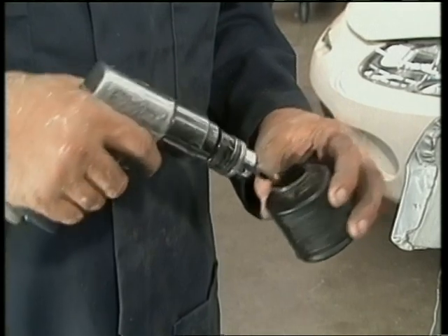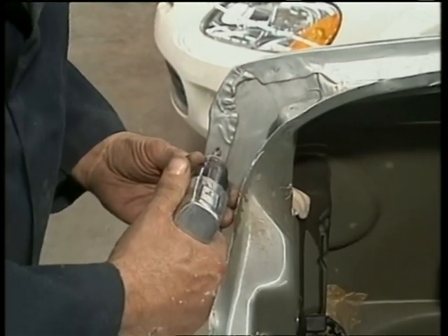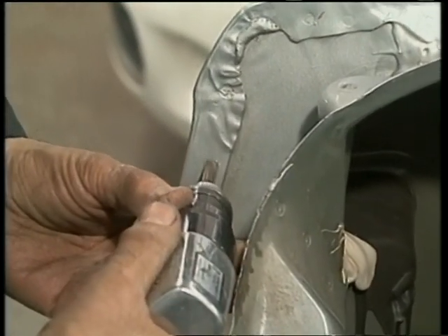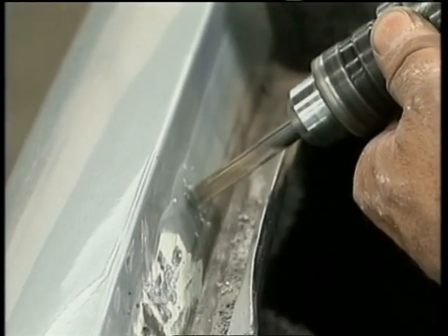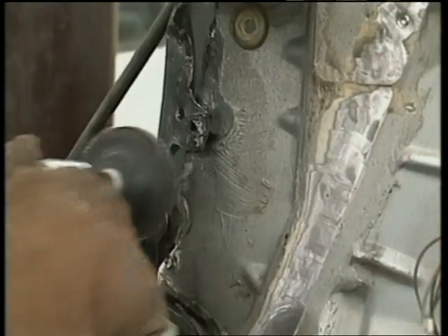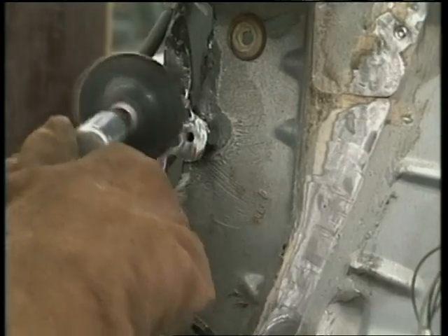A spot weld cutter is a tool designed specifically for removing spot welds in body panels. It's basically a specialized drill bit. A spot weld cutter cuts just around the area of the weld. Because it avoids the original weld, it's extremely efficient and can save a lot of time when removing panel assemblies. Once a panel is free, all that has to be done is to grind down the original spot welds.